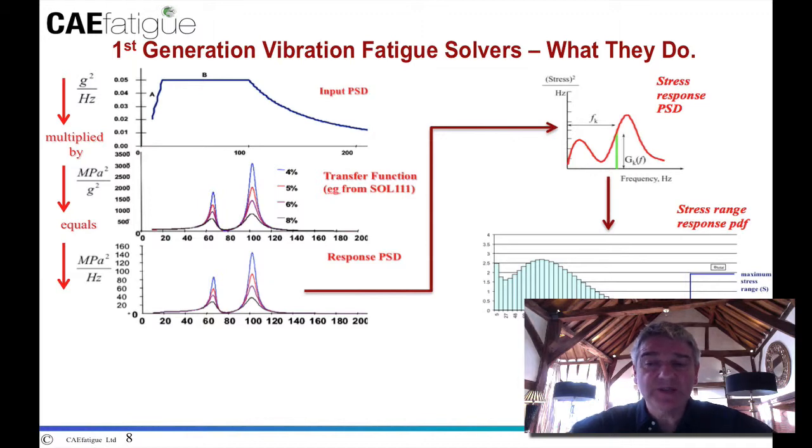So for the last 50 years, since the introduction of powerful finite element solvers like Nastran, we have been enticed with the possibility of very powerful frequency domain stress and fatigue solutions. Such first generation solvers do exist today, but they are severely limited in terms of model sizes that can be analysed, the type of fatigue solutions that can be employed, the form of loads that can be applied, and finally, they are typically restricted to single input systems.